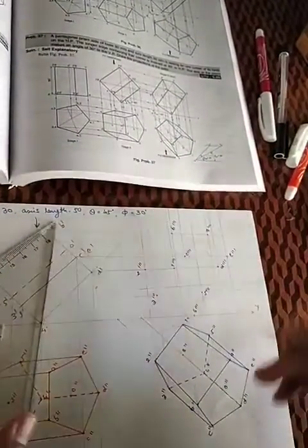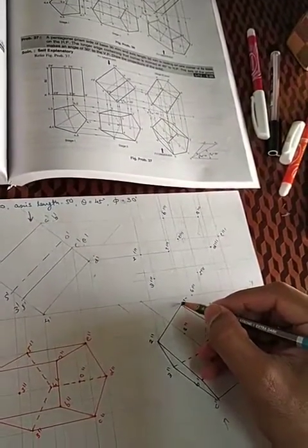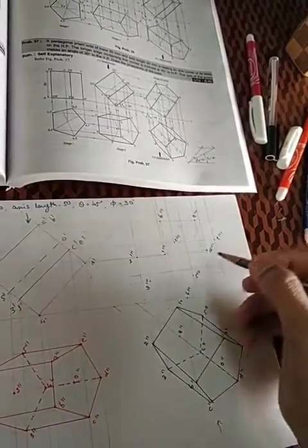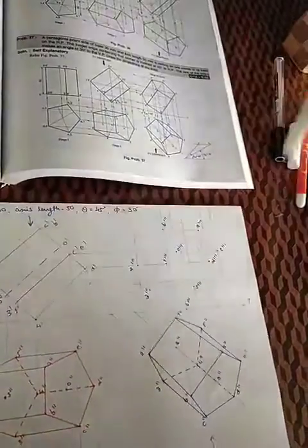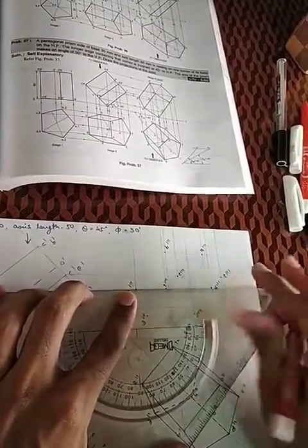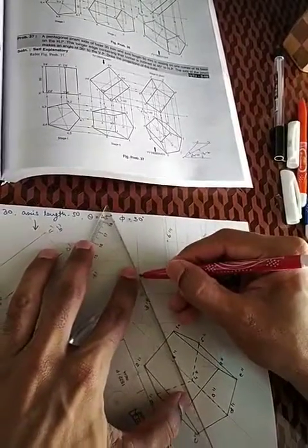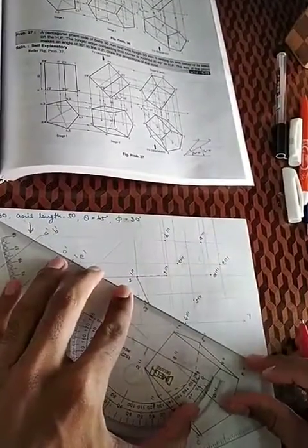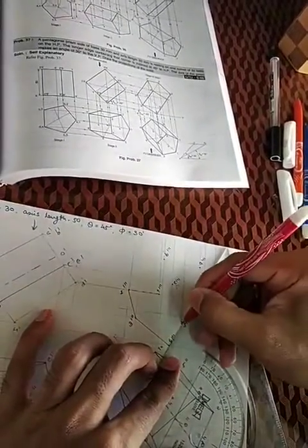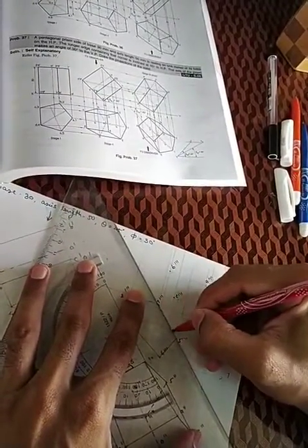As I can see here, in your next stage your observer will be here, so that this point number 1 will be invisible to him. So the line joining with 1 will be dotted, the rest of the lines will be full lines, right? So let's draw this. 1 is joining with 2, so I can join 1 and 2 with a dotted line. 2 to 3, 3 to 4, 4 to 5, and again 1 with 5. So the line joining with 1 will be dotted.